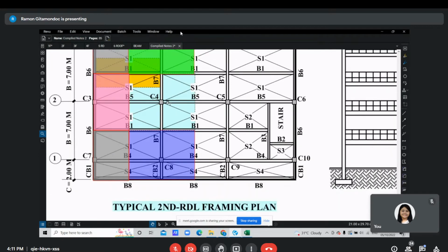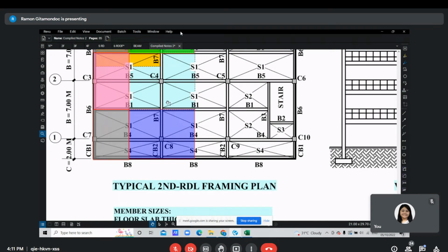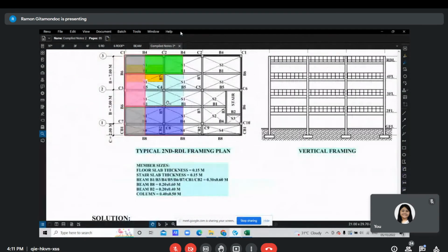Okay? So to calculate the weight sa tungkuan, it's just unit weight multiplied by the volume. And volume of concrete will be simply the cross-sectional dimension, the width times the height, and you multiply it with the length. So mura na siya ang mga basic nga principle. So, as regards computing the weight of the slab sa beam o sa girder, sa column, no? So length times width times height, okay, or width times height times length.